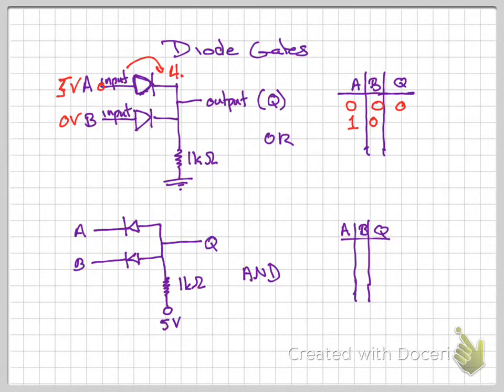So this is 4.3 volts on that side of the diode, and it's 4.3 volts over a 1K resistor. There's a 1K resistor there, so it's not shorted to ground. So this right here is 4.3 volts, and so the output is 4.3 volts. That is considered high because, again, it's CMOS or TTL, which this is neither, but it's within range. Let's just say high is 3 to 5 volts, and low is 0 to 1 volts approximately.